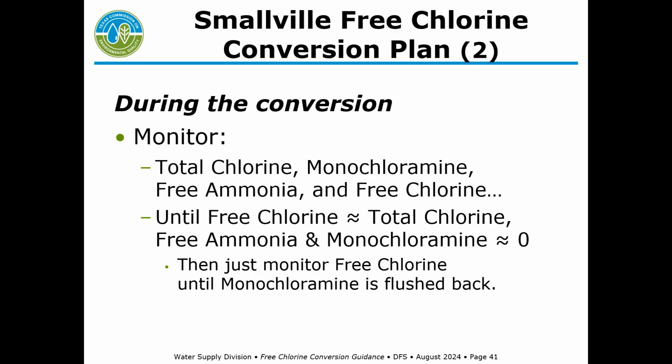You don't have to run all 4 of those tests for the whole 3 weeks or month or whatever your conversion is. It's just during the flush periods at the beginning and end that you need to run all 4 to be sure where you are with your residual.